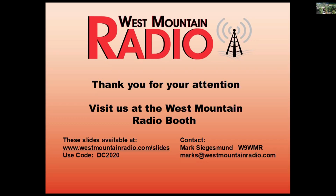A quick question. Is the PowerGate probably the best thing to use if you have a solar panel and you want to hook it up with a little battery? And does that do the charge regulation for you too? Yeah, it takes care of the charge controller part of it, and that's one of the big features. If you're going to use a solar panel, you just buy your charge controller on Amazon or something. It's going to be noisy. It's not going to be suitable for radio use. So one of the things we did in the design of the Epic was to put a charge controller in there that's radio friendly. So yeah, that's probably your best situation.